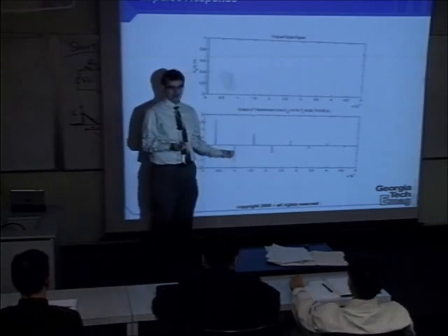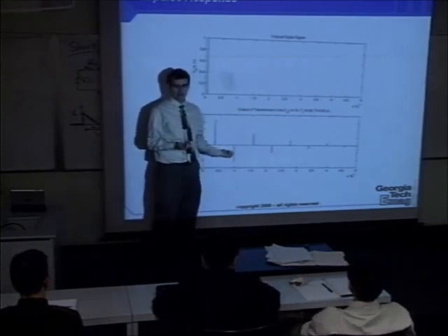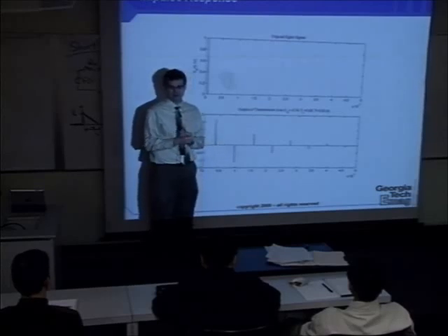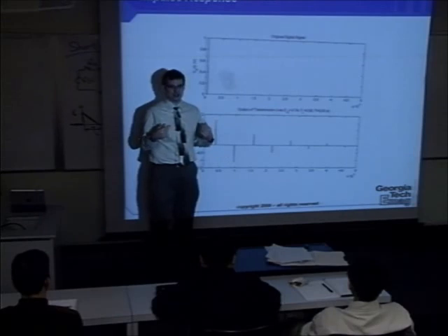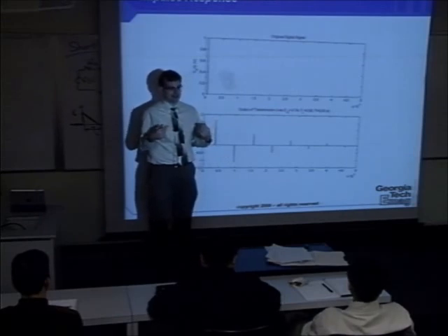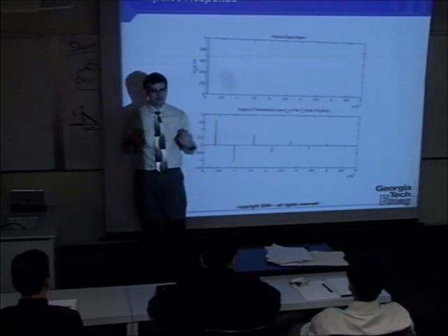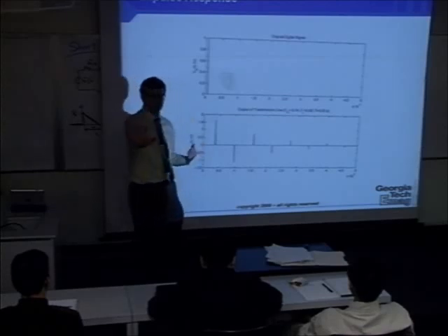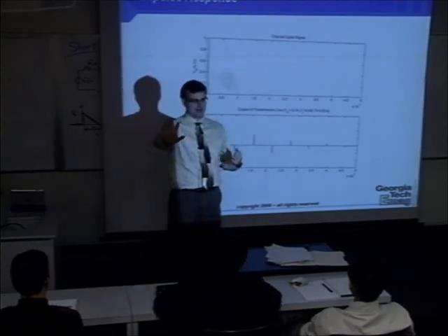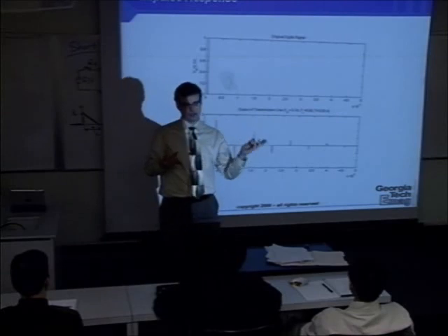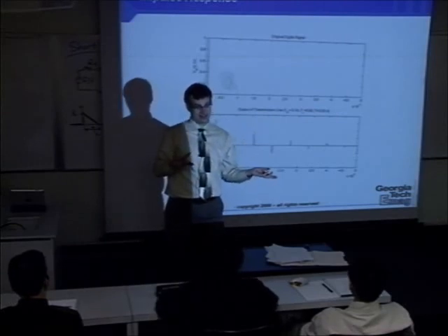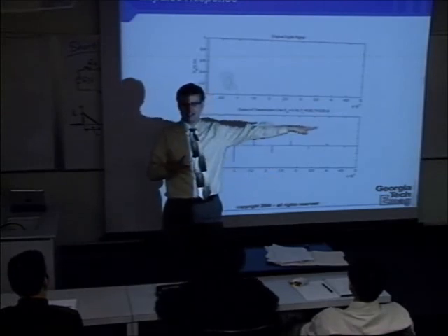And so if I have an impulse response, what does that enable me to do? Think back to your signals class. The next few minutes, this is going to turn into a signal processing class. If I know the impulse response, then I can take any shaped pulse and figure out what the output is of this linear system.